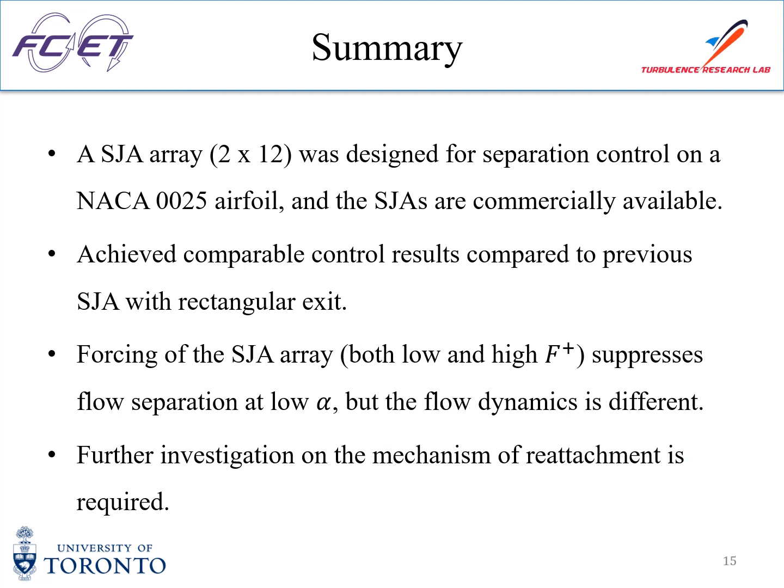As a summary, a synthetic jet actuator array was designed for separation control on the NACA 0025 airfoil, and the synthetic jet actuators are commercially available, so they do not require custom manufacturing. It can achieve comparable control results compared to the previous synthetic jet actuator with a rectangular jet exit, which Mark Fero has been using.